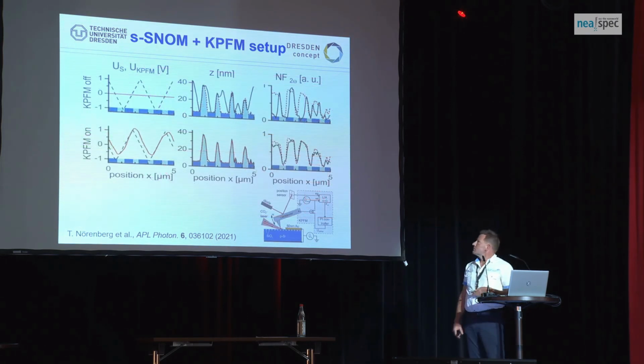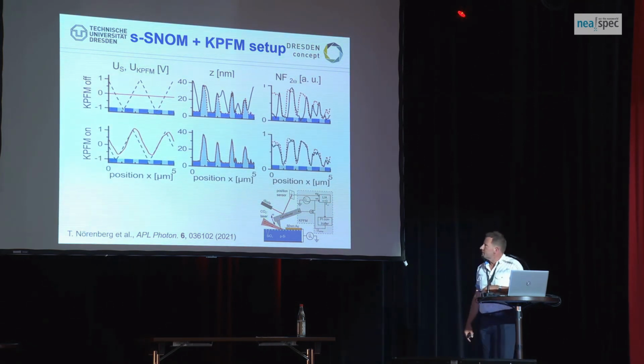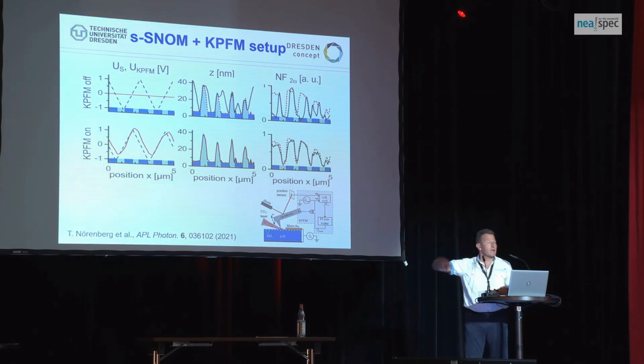Second experiment, we go for line scans. We take the test sample, made of p-doped silicon and silicon dioxide, and scan along that line. At the same time, we apply a certain modulation voltage, U_S. You see this triangular, zigzag voltage here, simply to test how well our regulator is working. You can really test the speed of your PI control with this. And that's exactly what we've done.